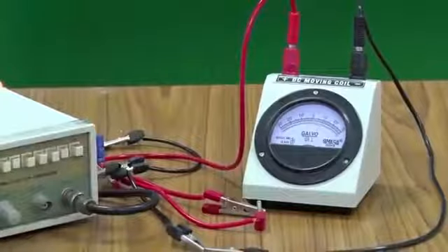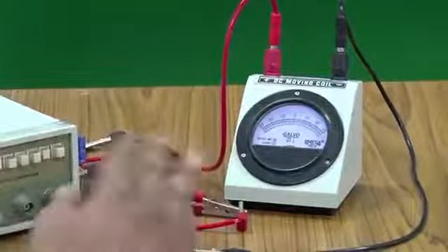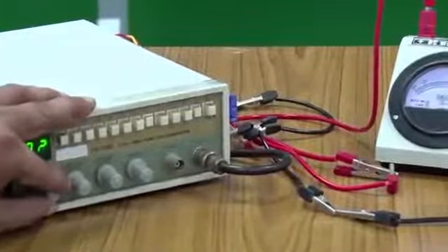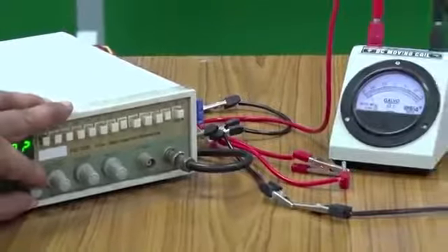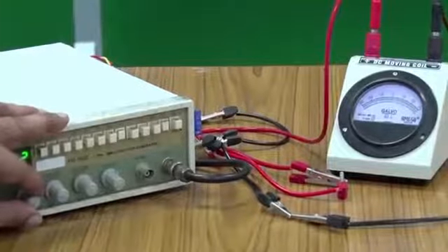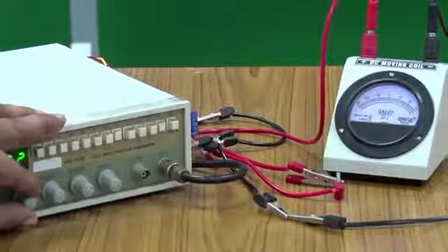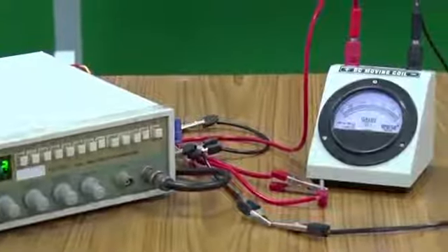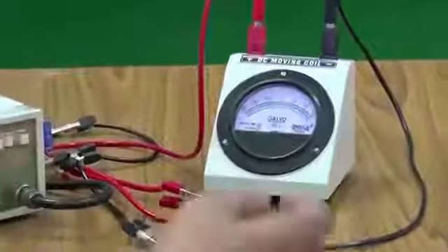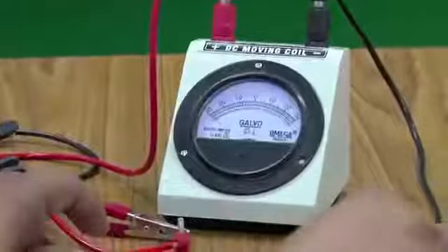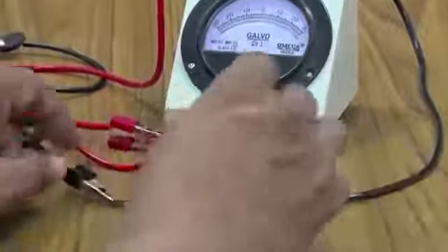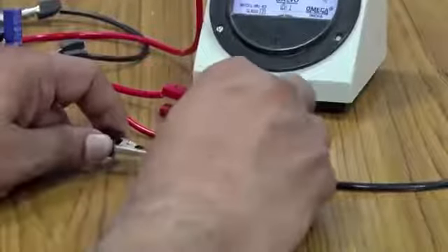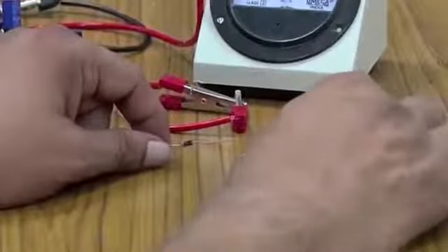So you can see that the needle going on both sides, this side, that side, this side, that side. Frequency I can further decrease or increase. So I am decreasing the frequency. This is the minimum I can do. If I increase the frequency, it will go more quickly. Okay, so it is in AC. It shows that it is in AC. It is changing directions. Now, in between, let me put this diode. In this circuit, let me put the diode. So, I put this diode here.